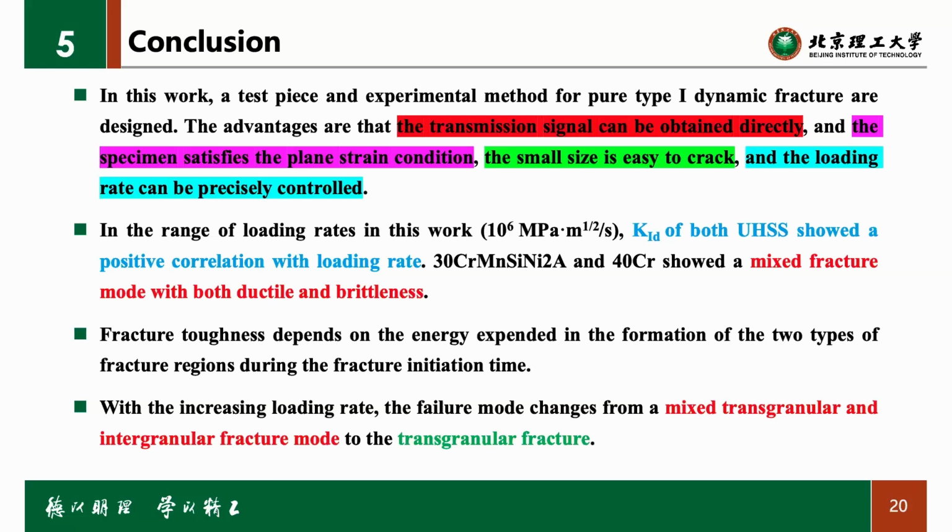And it should be noted that the strain gauge method is useful to measure the crack initiation time for the Model I dynamic fracture or dynamic bending.